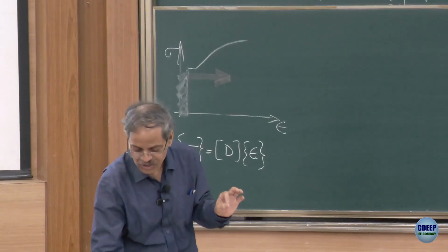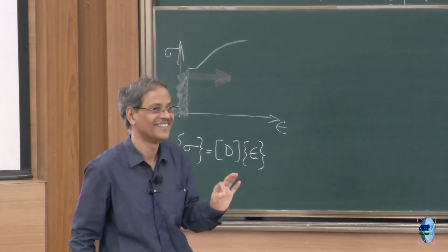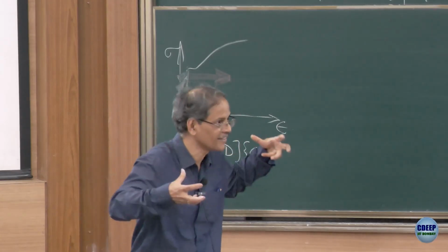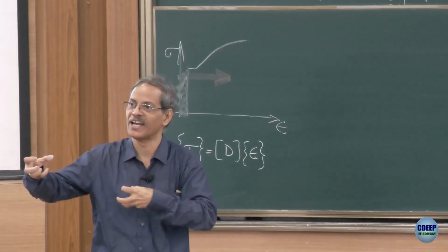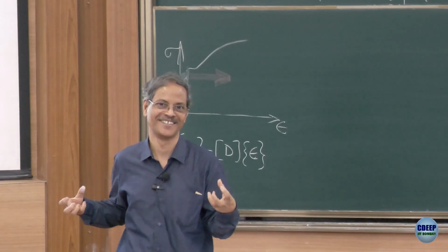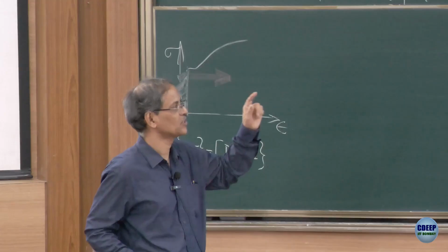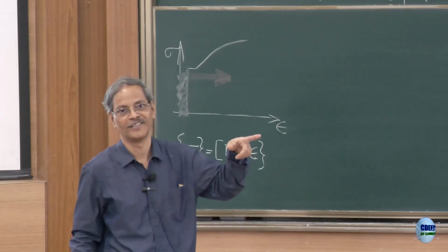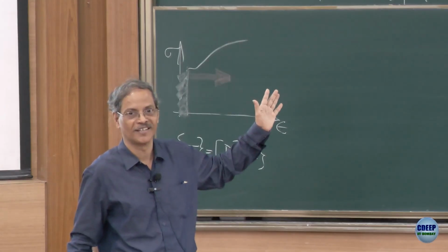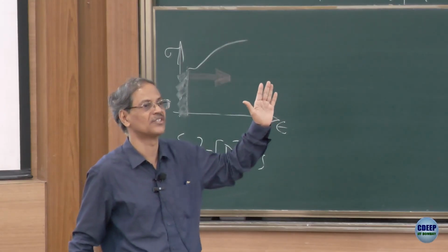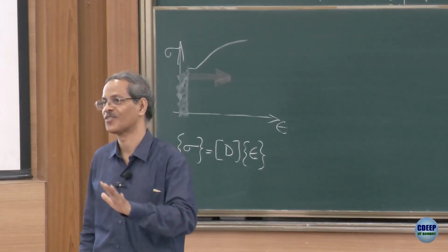What will be a 0 or a non-zero in this matrix represent? It represents a certain coupling between one form of stress and another form of strain. When you have 0, 0 in the first and second row, third column, it means that the normal stresses are not coupled with the shear strain, which may not be true if it is a composite material.